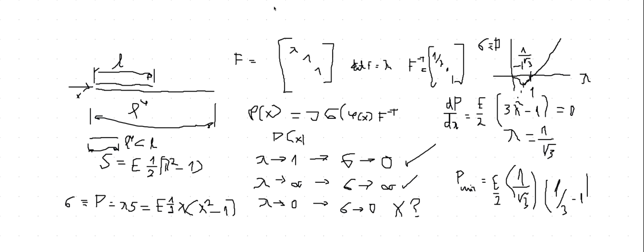So that happens to be the stress strain diagram for Saint Venant-Kirchhoff material, and obviously that doesn't make any sense. Basically, you have the result that if you have very large compressive deformation, you need zero stress to apply this deformation, which is certainly not physical.